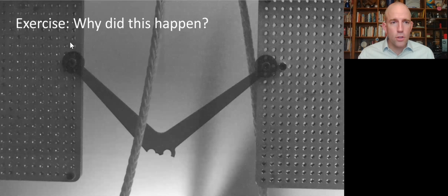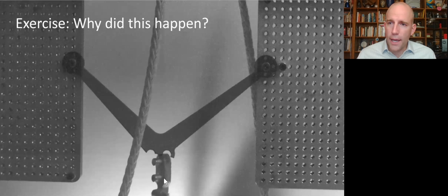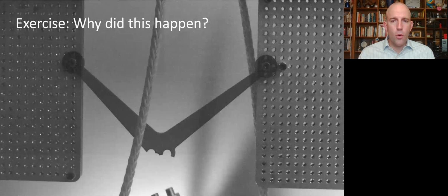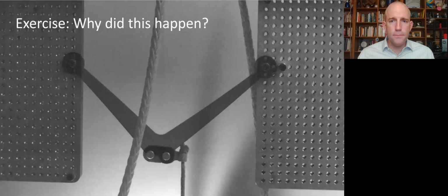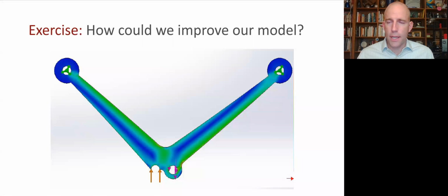So everything up here looked plenty strong, and here was where we had the weak link. Now, how did that happen? Well, if we go back and look at the finite element analysis of this component, we can see that a relatively simple load was applied here, where it looks like the force was evenly distributed around the whole interior cylinder of that hole.